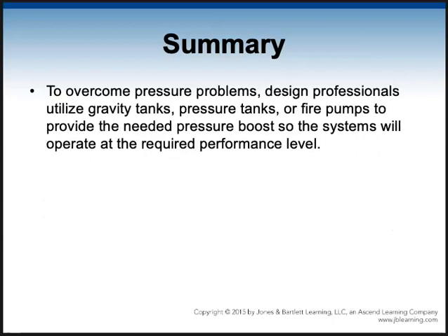Lastly, to overcome any pressure problems, we're going to add gravity tanks or pumps to systems to boost where we need it, especially in high-rise buildings or very large buildings like a Walmart or a Costco, where they're extremely large and we need to have water all the way to the back of the building as well as to the front. Okay, sorry that was a little longer than I hoped it would be, but this is a really important one, understanding how the water gets there.